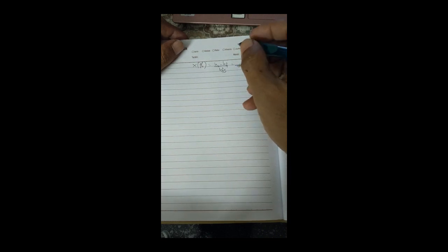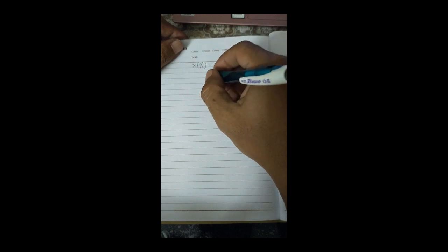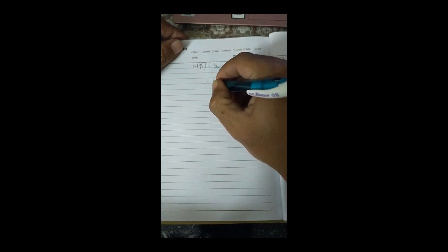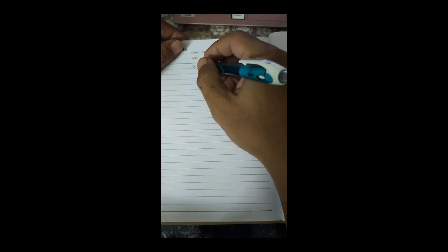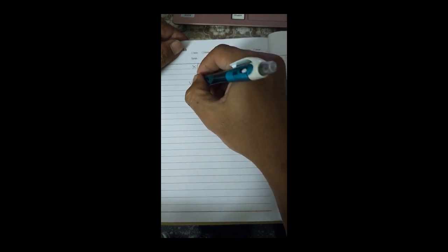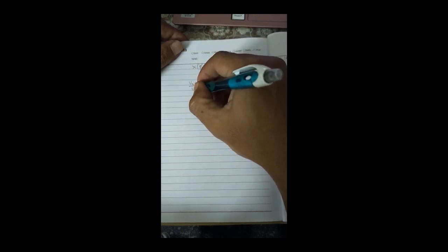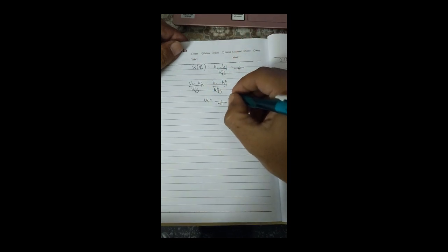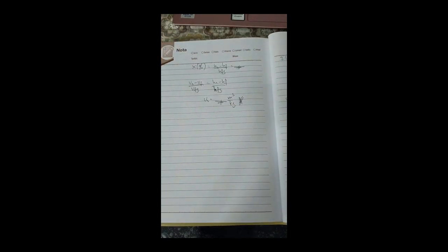Okay, from here we can also have the fraction. Also we can determine the value of specific volume: V2 minus Vf2 over Vfg. So V2 is in meter cube per kg. Alright. Okay, thank you.